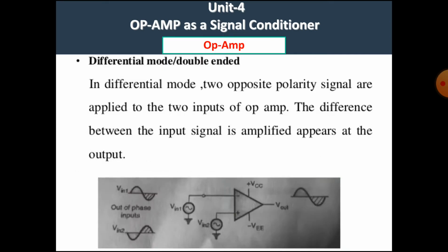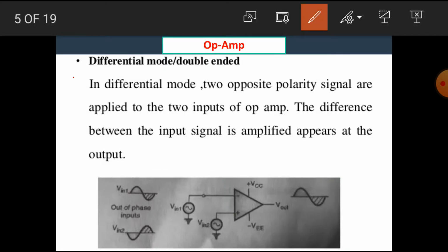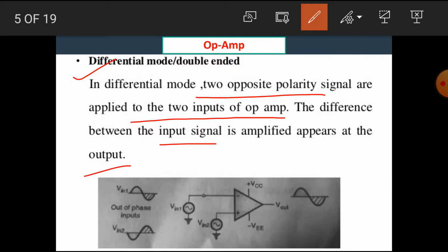Okay, similarly we can see the differential mode or double-ended mode. In differential mode, two opposite polarity signals are applied to the two inputs of the op-amp. The difference between the input signals is amplified and appears at the output.